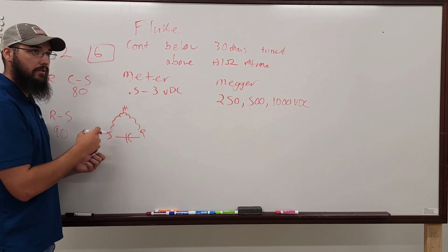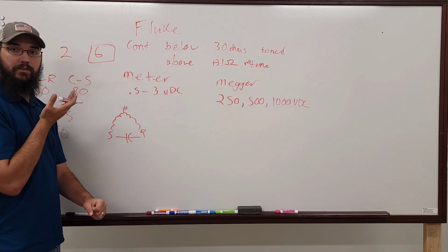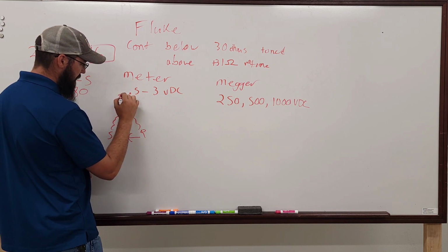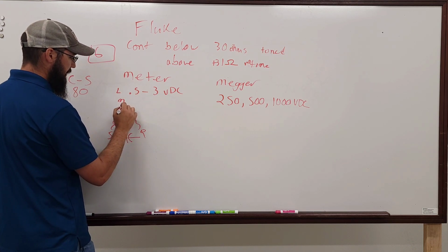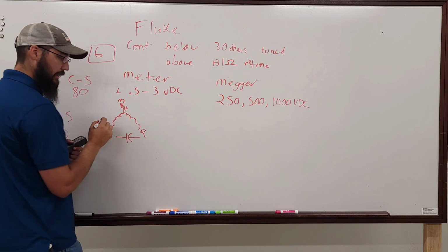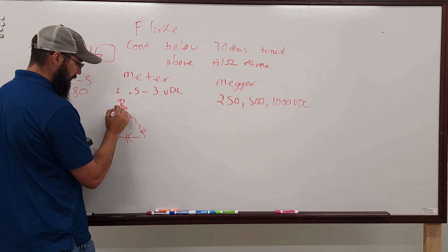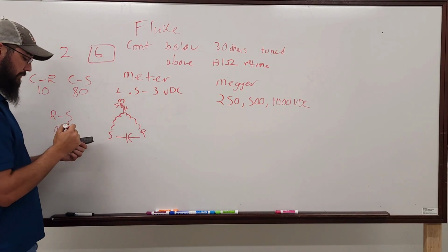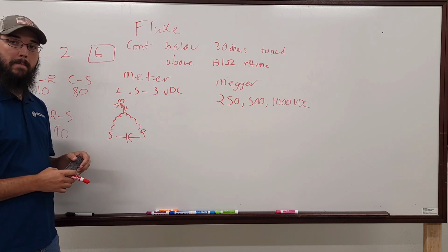By adding to that coil, allowing less flow because there's more resistance against it, it's going to turn slower. Between here and say we have a medium speed and a low speed. This could be a winding, or it could be an actual resistor, and it really just depends on the motor manufacturer. So as you increase that resistance on the speed taps, it decreases the motor speed.